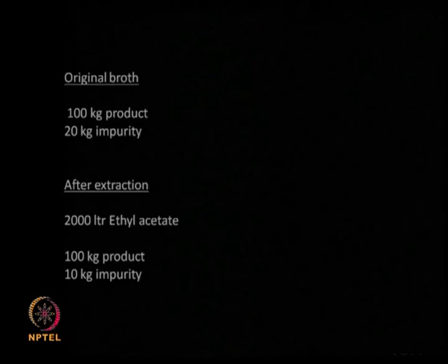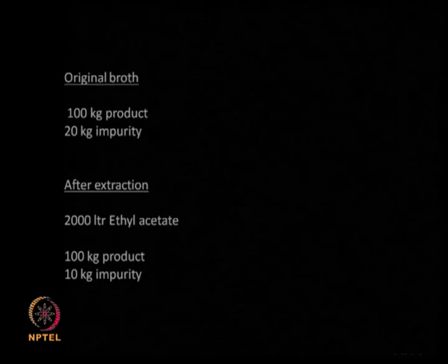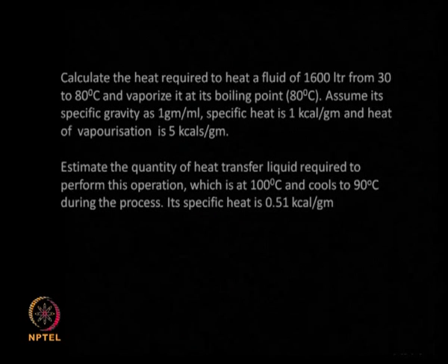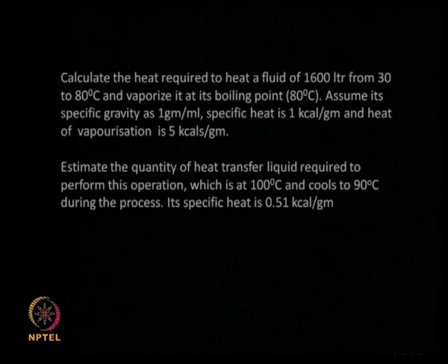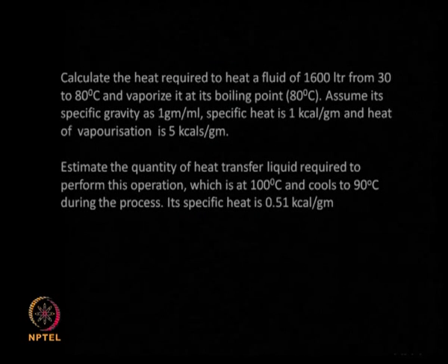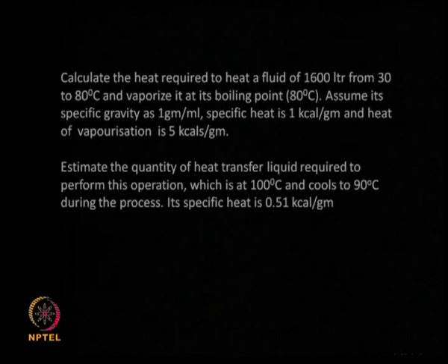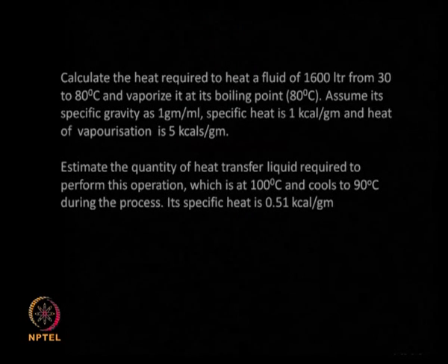Now having looked at two different mass balance type of problems, let us look at a heat balance problem. This is also very relevant when you are heating a fluid, when you are vaporizing a fluid, when you are performing a fermentation type of process where the reactions are carried out at a higher temperature, then you need to calculate the amount of heat required to heat a fluid, the amount of heat required to vaporize a fluid, and then also calculate what should be the quantity of the heating fluid required.